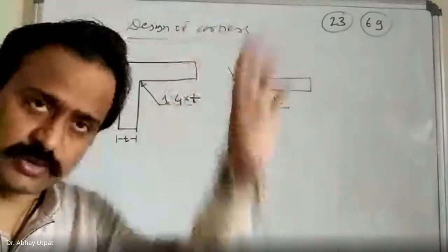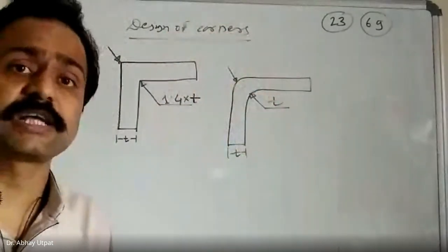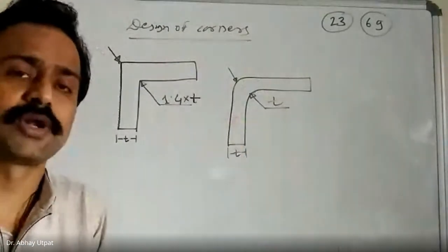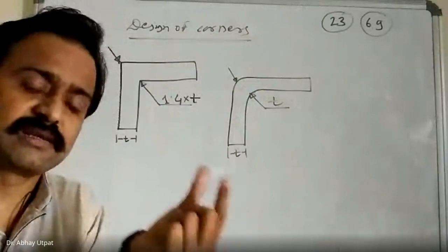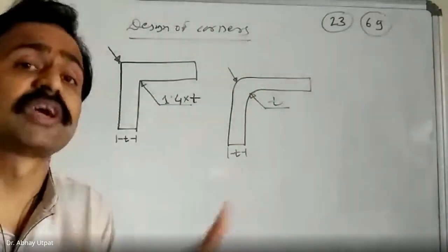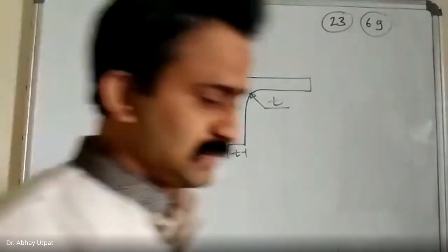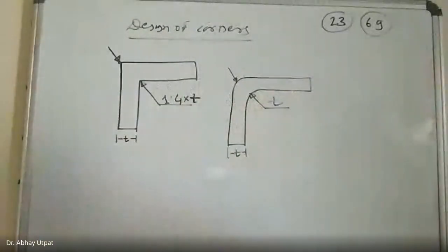That aspect is totally different. Here, we are talking about the manufacturing aspect. When you are going to solidify your component, the thickness will affect the cooling rate. So that's why, while designing parts, sharp corners are avoided.